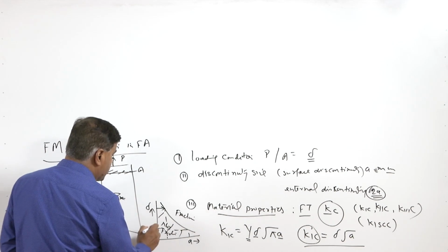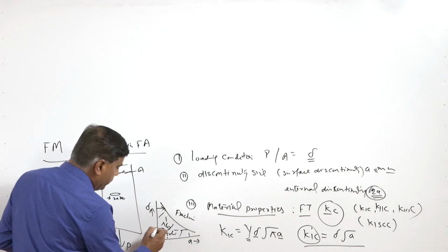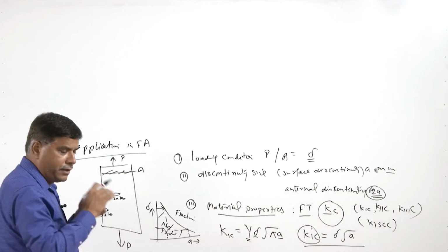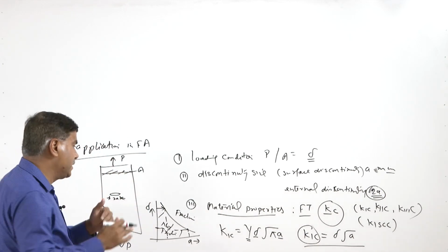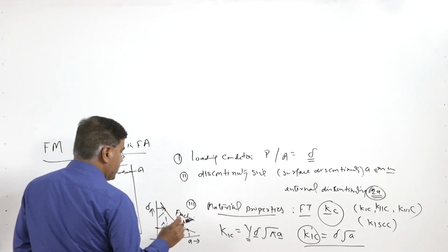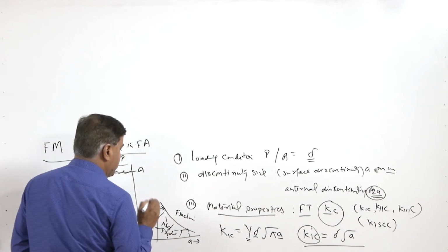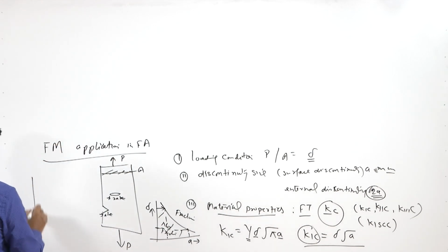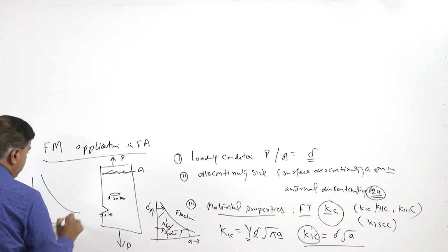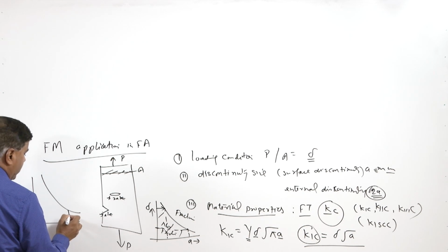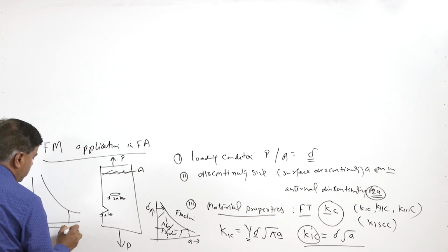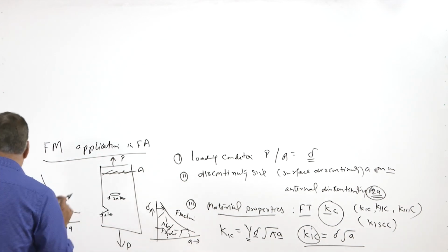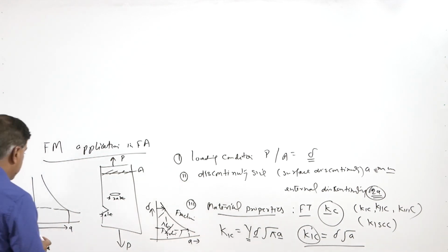So, for low stresses the tolerable size of the discontinuity is larger as compared to the case of a higher stress value. It can work either way: if larger discontinuities need to be tolerated, then the applied stress should be reduced.